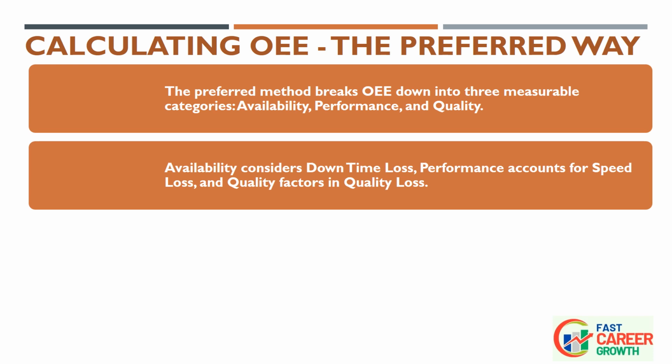Ideal cycle time is the theoretical fastest possible time to manufacture one piece. Therefore, when it is multiplied by total pieces, the result is net operating time, the theoretical fastest possible time to manufacture the total quantity of pieces. Here is a simple example of a performance calculation.